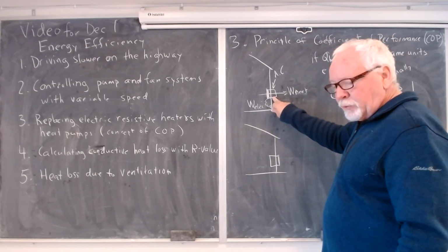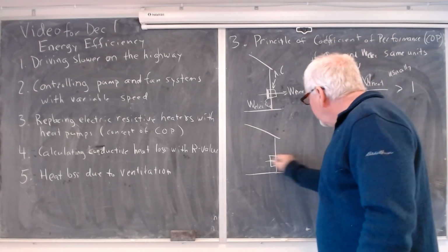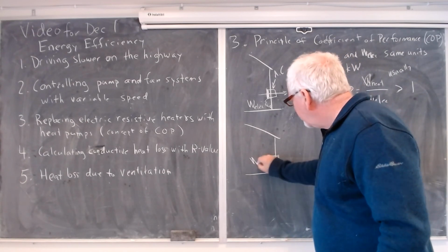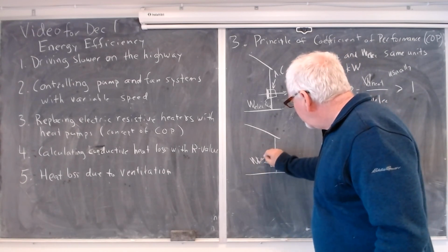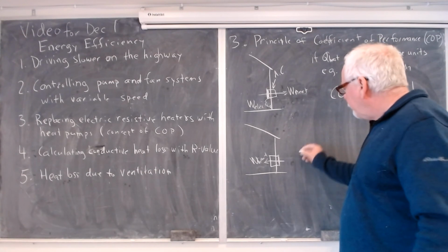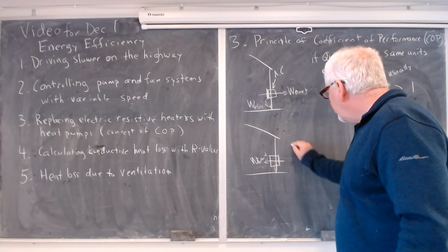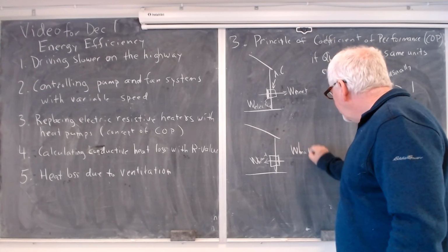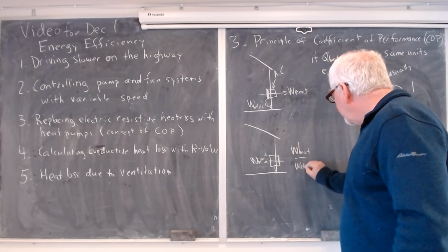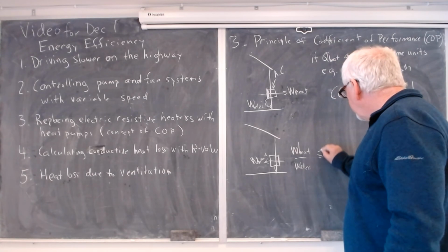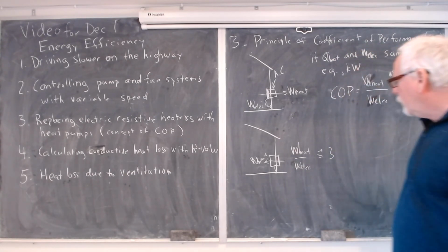If I took the room air conditioner and flipped it around, it would be pumping heat in, and for roughly the same COP. Okay, W heat over W electric would stay the same at about 3.